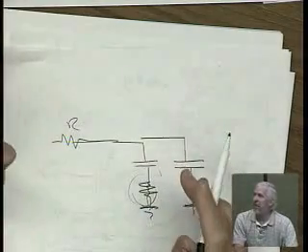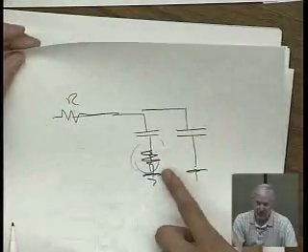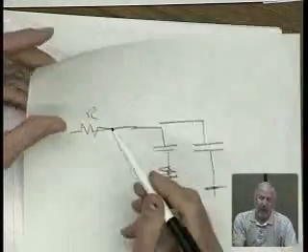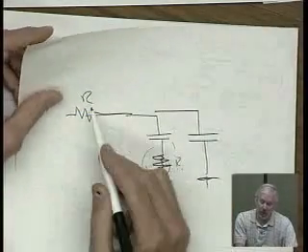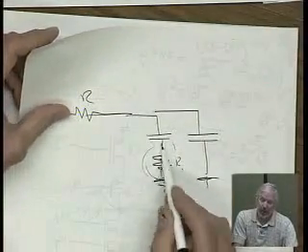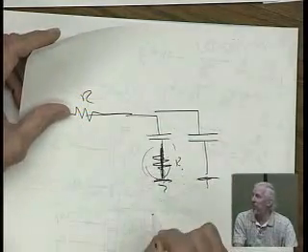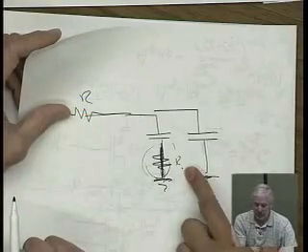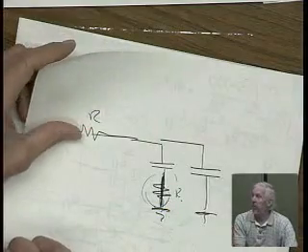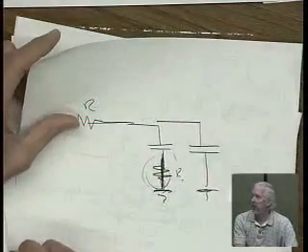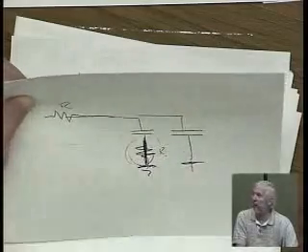You actually helped on this one, because I've been looking at it. Everyone else is taking this directly to ground, and I didn't think you can do that. If that resistance here is much, much smaller than this one, then that zero's at such a high frequency, and it's probably a pretty good approximation to make this ground. I'm asking what would I do if this is not as small. You're going to have to work it out, small signal. It's just an RC thing, right?